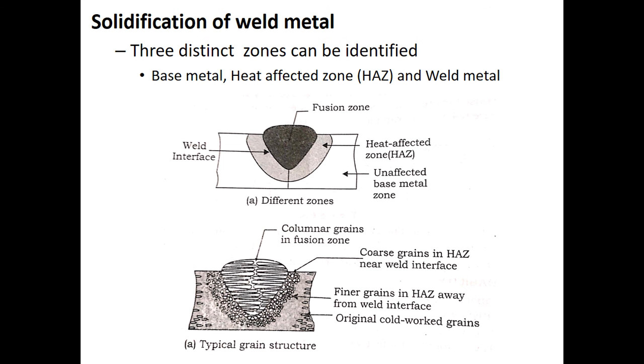Why does it have coarse grains? Since the cooling occurs very slowly. As a result, the weld metal has very low strength, toughness, and ductility values. And how can you modify these properties? Of course, by using a proper filler material or by doing appropriate heat treatments, all the heat treatment techniques like annealing and normalizing. By doing those techniques, you will be able to improve the mechanical properties.